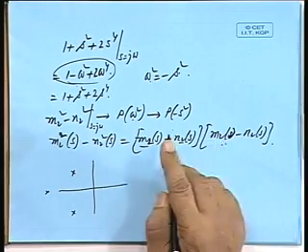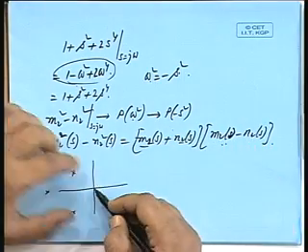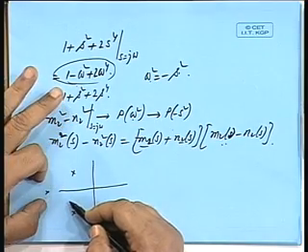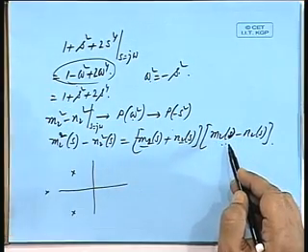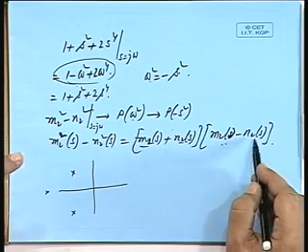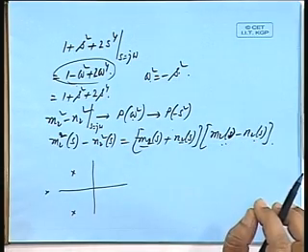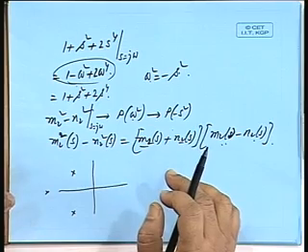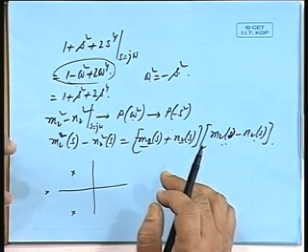So if you are having a polynomial containing roots in the left half plane, then if I take just the negative sign of the odd terms and generate another polynomial, then that will have roots in the right half plane, just the mirror images. This is something very interesting.